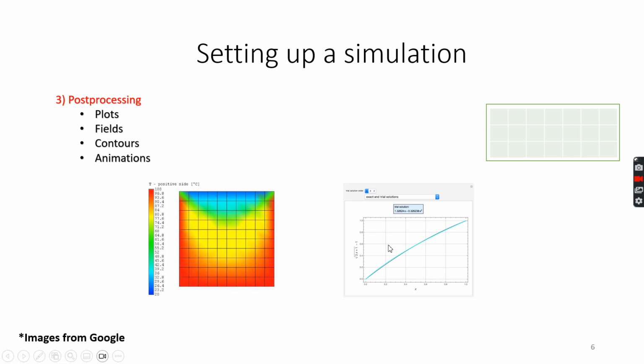If you set up the geometry and the meshing very accurately, that means there are no corner edges and they're properly patched, and the meshing is done very fine, and it has attained grid independency, almost 50 to 60% of your solution accuracy is determined from that part itself.